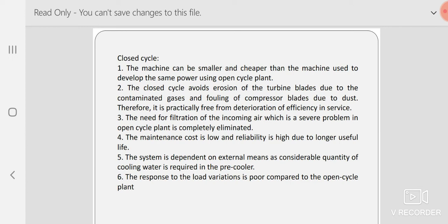In case of closed cycle gas turbine, also you have maintenance. You have maintenance because of the cooling tower you have provided that requires water. So you need water also. You need a filtration system also, and accordingly the system is to be designed. Now again, it depends on the availability of the resources. As an engineer, you have to decide if the plant is coming up in Chennai. It's a big problem because water is a big problem in Chennai.